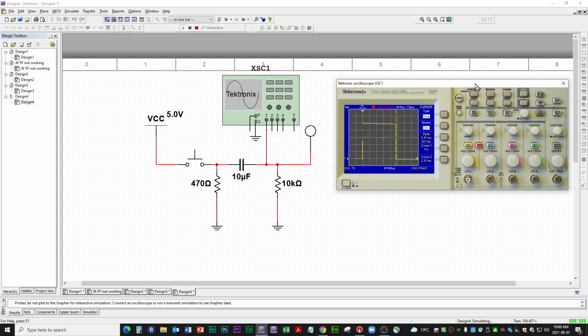Okay, now can we do it again? Sure we can. Now we have the references set up here, the voltage reference is set up here. Let's see if the pulse looks different. All you have to do is press the single sequence again. The simulation is still going. Sometimes it works, sometimes it doesn't, but I think this time it's going to work. I'm talking about the Multisim simulation, not real life. Press single shot or single sequence. The screen gets cleared, the scope is in listening mode. Anything that comes up, it's going to register.